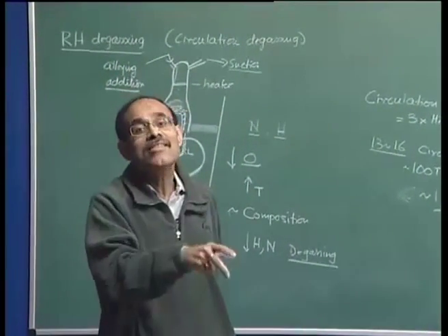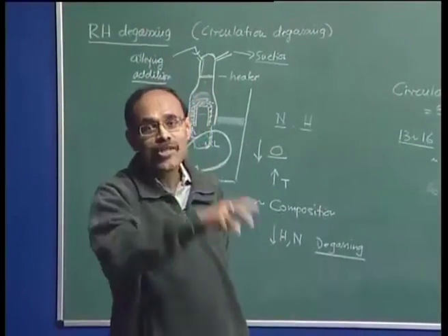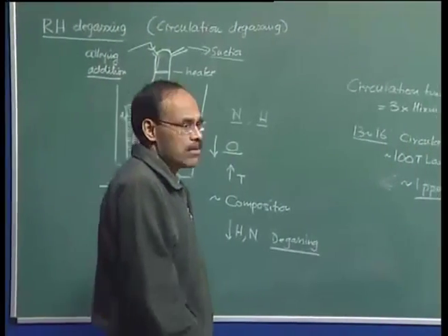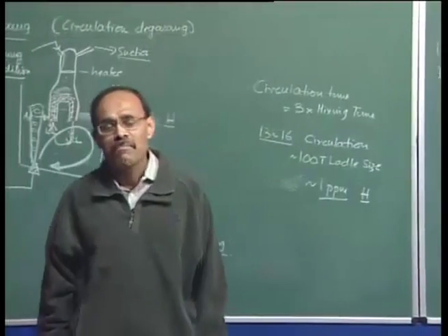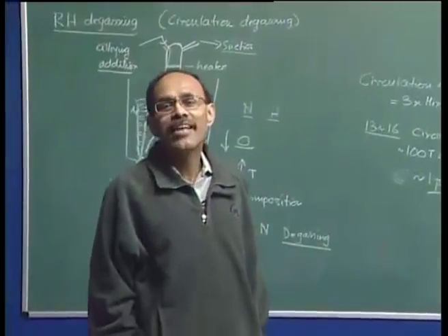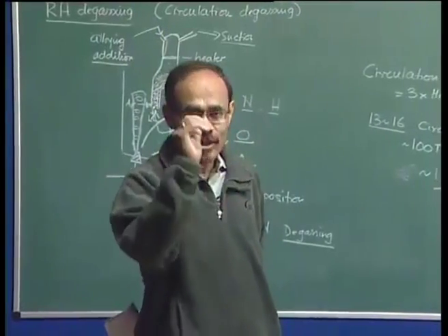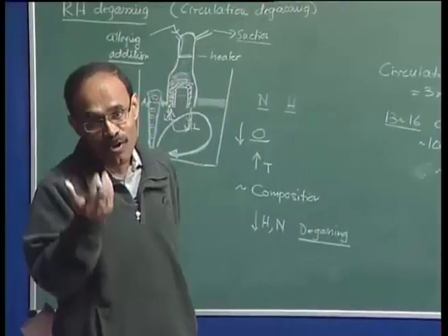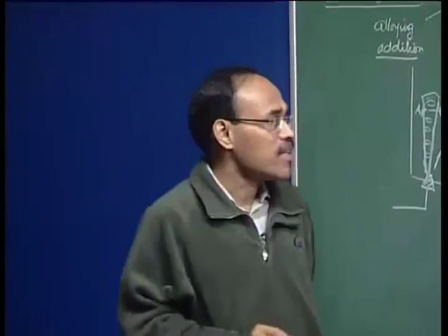because more silica means more temperature, more silica means more slag volume, more silica means more lime. So if we cannot eliminate a lot of sulfur in blast furnaces, sulfur removal cannot be achieved to a significant extent in the basic oxygen steel making furnace, because the conditions thermodynamically are not favorable there. We have a high oxygen potential, and we all know that sulfur removal is not facilitated under an oxidizing environment.